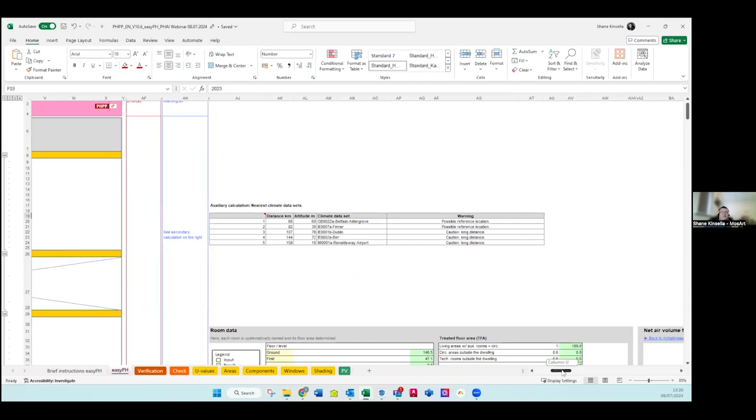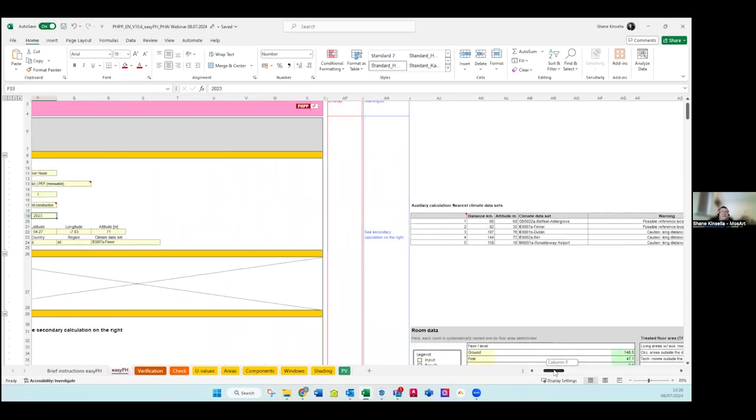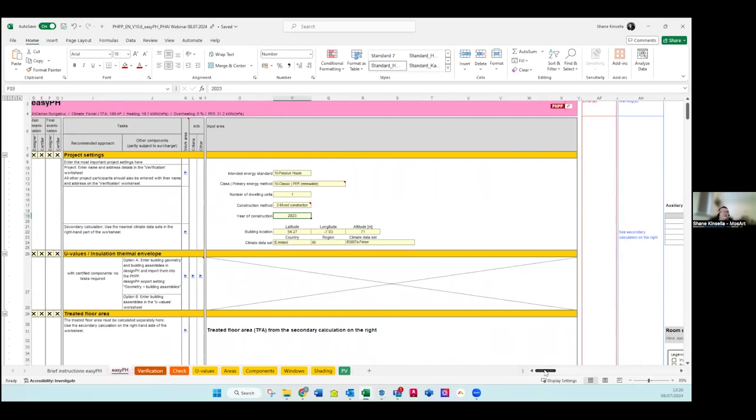So I suppose don't ever be in doubt if you're concerned about that aspect of it. We've used a thinner weather file here. We've got obviously the various options. We can pick the closest here. You could look at your location and see what's the best weather file to use. Again, if you're in doubt, consult with your certifier on that front.